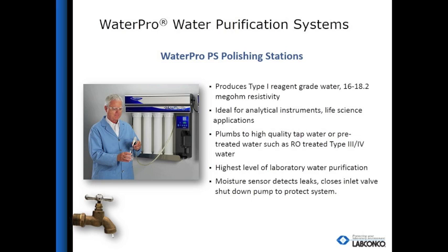The HPLC, UF, and HPLC-UF hybrid also incorporate UV reactors and organic absorption filters to further reduce total organic carbons, or TOCs. The ultrafilter is added for the reduction of endotoxins.